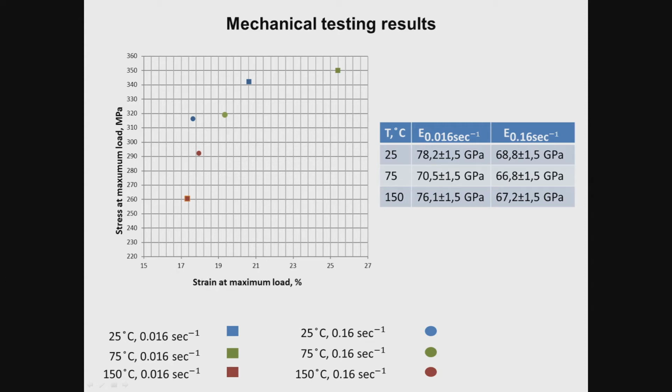As for strains at maximum load, they also decrease by 8%, so this point and this point, and by 32% for this point and this point. This is for 0.16 and 0.016 strain rates respectively.